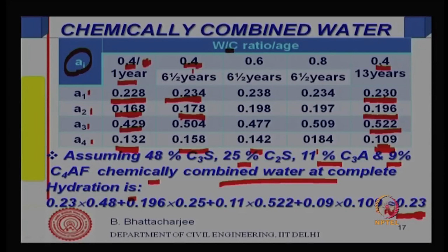So, generally, supposing you consider this as 55, this as 22 and this is maybe somewhat less, this value will change, but it is roundabout 0.23 only. So, values would change approximately, therefore, 1 gram of cement reacts with 0.23 grams of water for complete hydration.